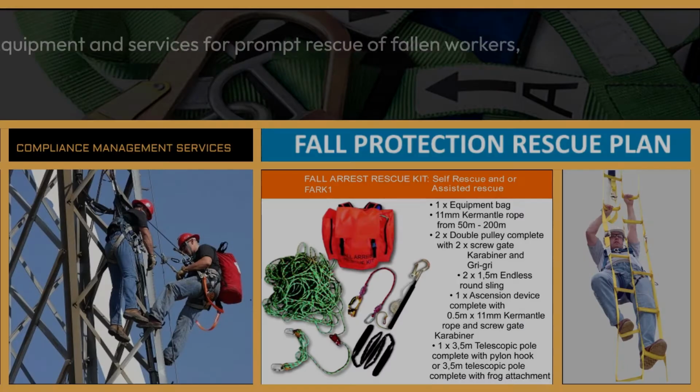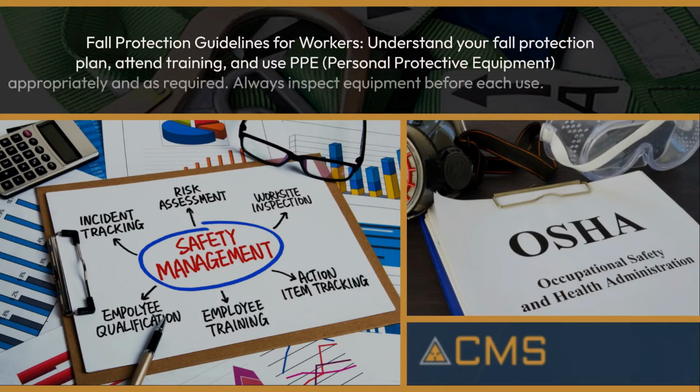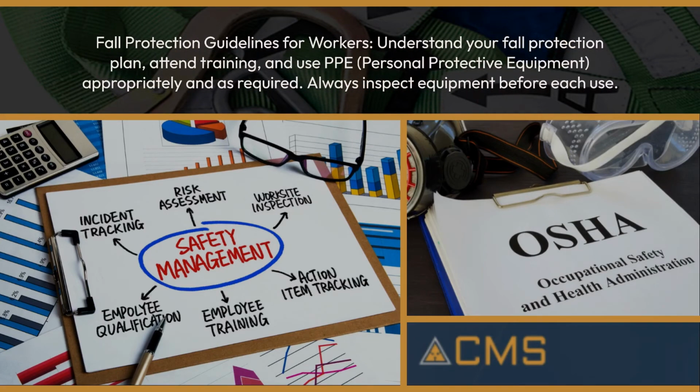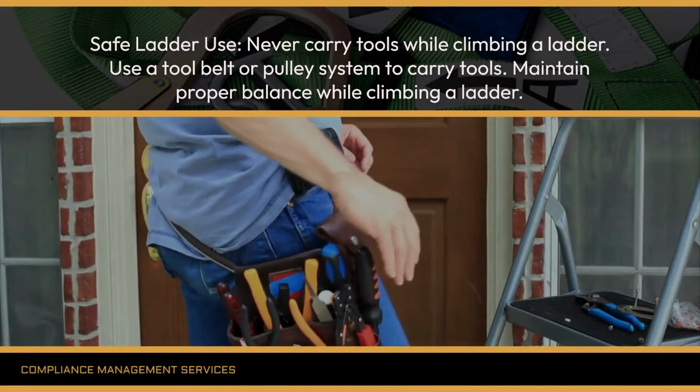Equipment and services for prompt rescue of fallen workers, including self-rescue, must be available before elevated work begins. Fall protection guidelines for workers. Understand your fall protection plan, attend training, and use PPE, personal protective equipment, appropriately and as required. Always inspect equipment before each use.